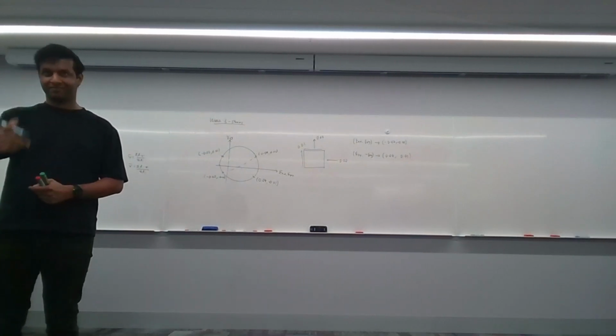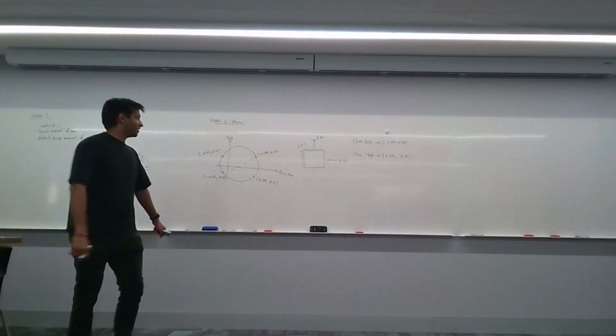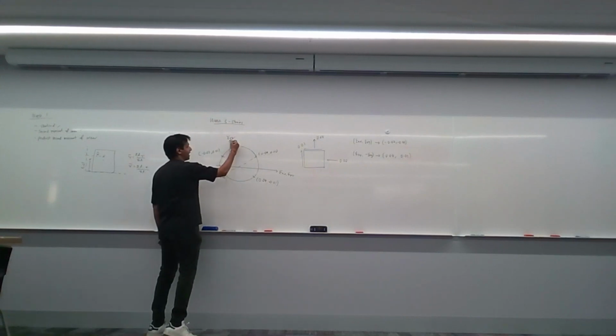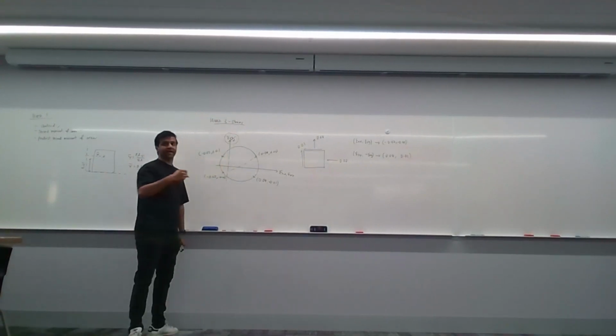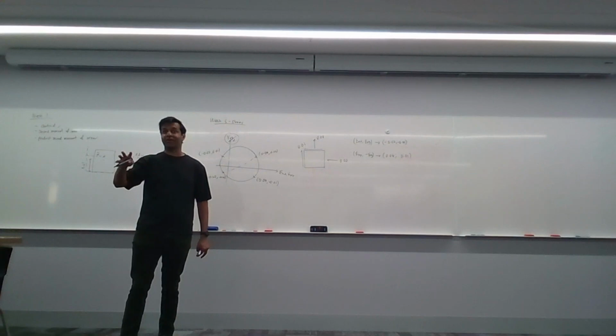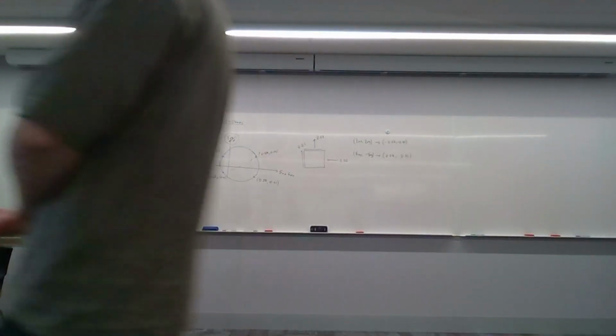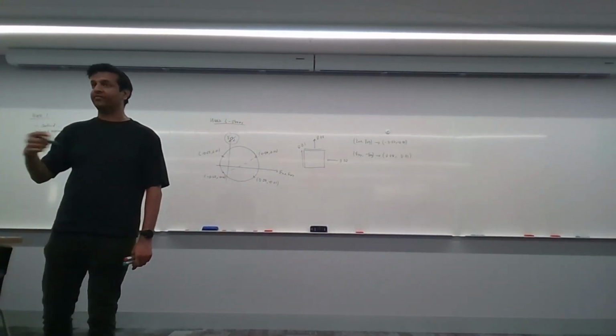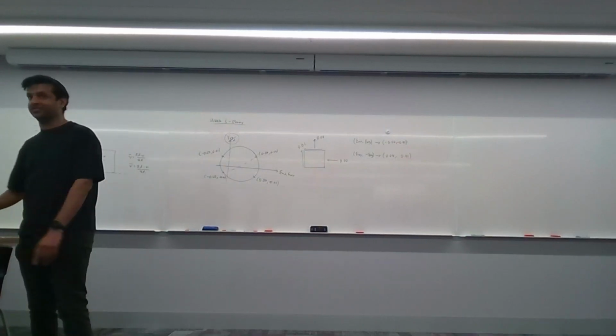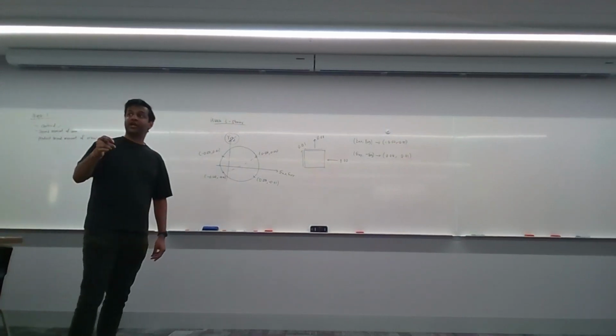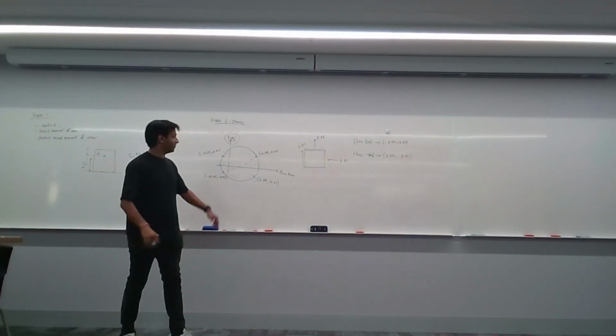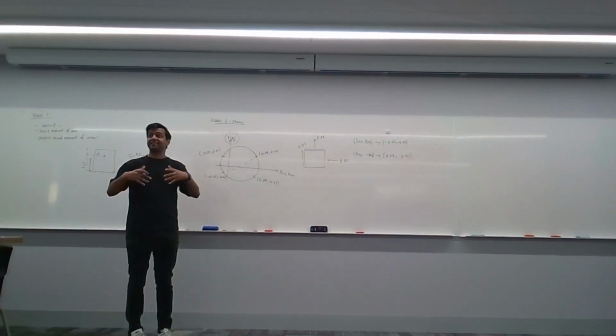You should divide it by 2. Very good. Remember, the y-axis always has to be gamma xy divided by 2. Believe it or not, this is one of the most common mistakes made in the final exam by students over the past few years. For strain, whenever you're looking at the Mohr circle, this needs to be divided by 2. Everything is in terms of divided by 2.